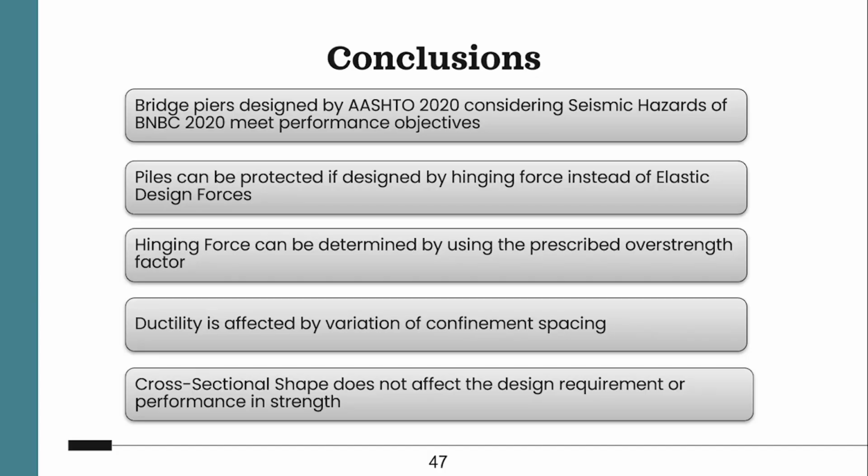Finally, our main conclusion is that the design guidelines that we have provided can provide a safe structure and meet the performance objectives, and the piles can be protected if designed by the hinging force instead of the elastic force. That hinging force can be determined using the prescribed overstrain factor that we have already discussed.